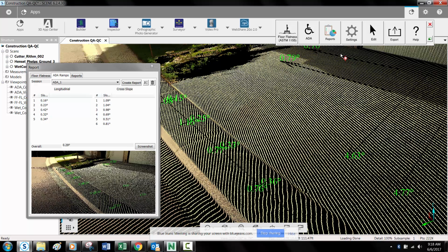I believe so. That's the slope. The direction of the slope needs to be less than 5 for the ADA ramp itself, and then the cross slope at 2.5 degrees max or 2 degrees max for water flow. But those are very important numbers that I should confirm and then send out to everyone. Thank you, Sean, for bringing that up. Very important.